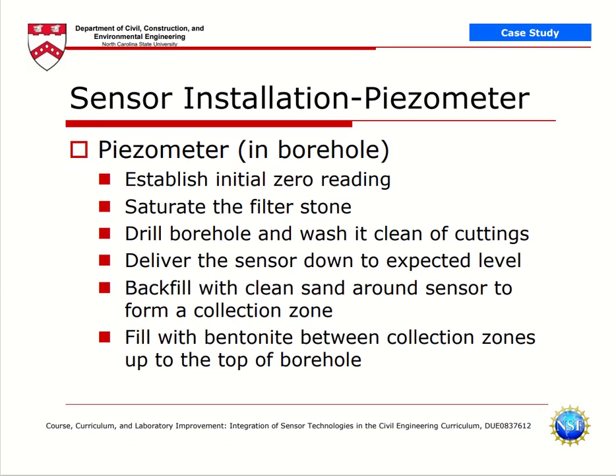Then they installed the piezometer in the borehole. This is the installation part that we are discussing now. First they established the initial zero reading. Then they saturated the filter stone. Then they drilled the borehole and washed it to clean off cuttings.